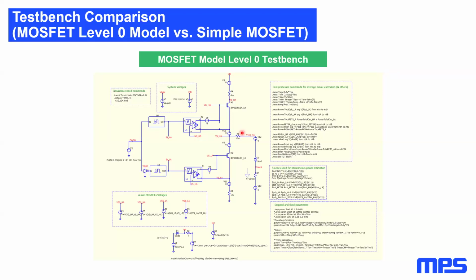Also, one could notice that this approach is almost equivalent to the power losses first-order calculation method that we have shown before, because both are based on the hypothesis that the switching node commutes linearly. We have also included an estimation of the PCB traces resistance, which we have aligned with the values measured on the PCB that we used for comparing all these estimation methods.